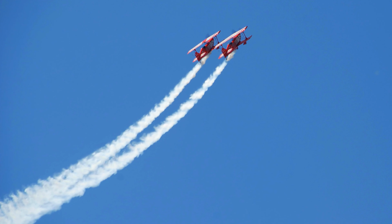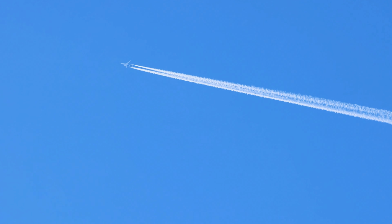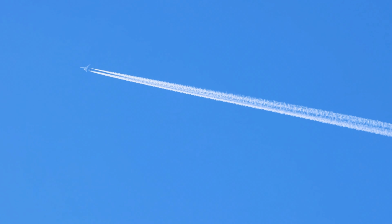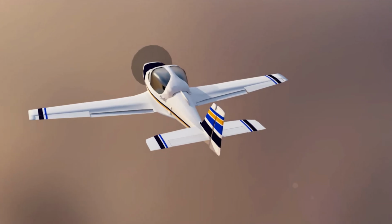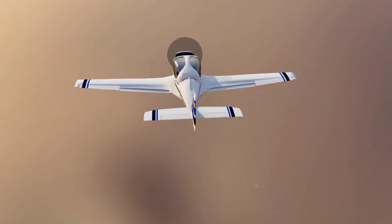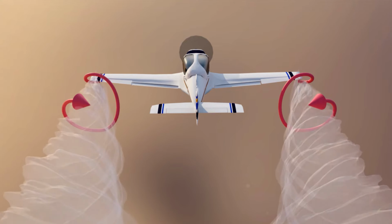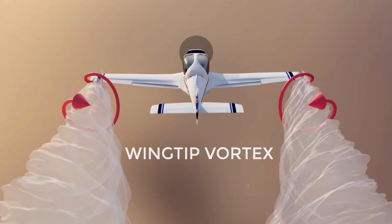What do you think happens to the air when an aircraft flies by? The exhaust coming out of aircraft engines looks pretty dangerous, generating huge amounts of thrust and pushing back tons of hot air. Would it surprise you to know that the most dangerous part of an aircraft's wake is not the engine exhaust? By far the strongest component of wake turbulence is the swirling air generated at the tips of the aircraft's wings. This circular motion of air around the tip of the aircraft wing is called a wingtip vortex.